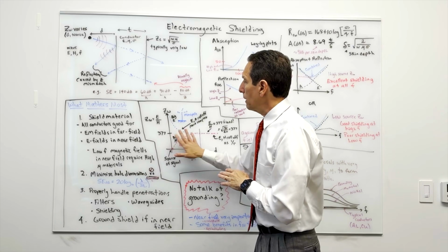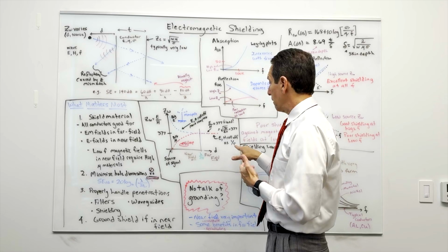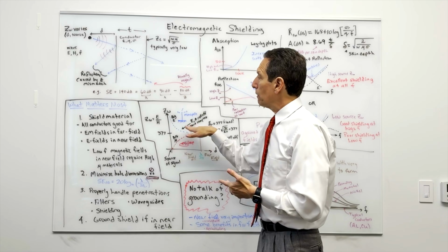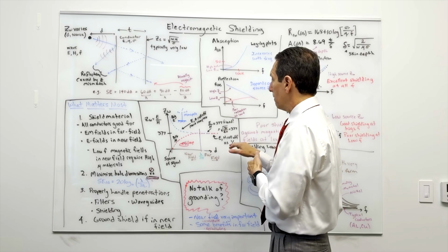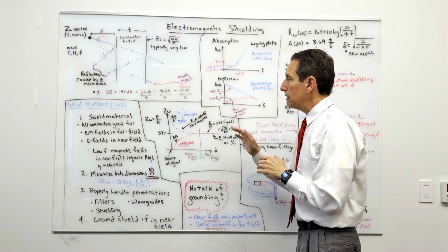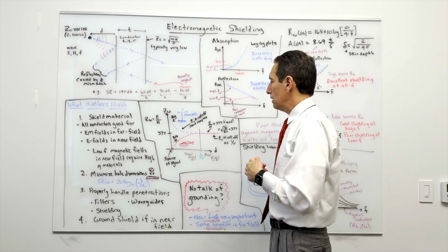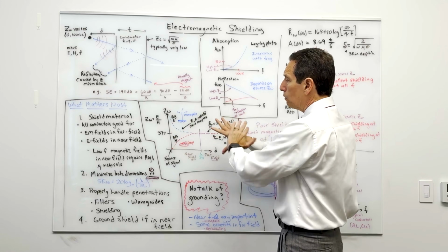Now notice that's not what happens here. E and H change very differently and much faster. So they're not 1 over R. They might be 1 over R squared or 1 over R cubed when you're in these regions here. They change much more rapidly with distance than when you're in the far field. Okay, and that's part of the theory behind propagating for radios and communication systems and stuff like this, this 1 over R understanding.